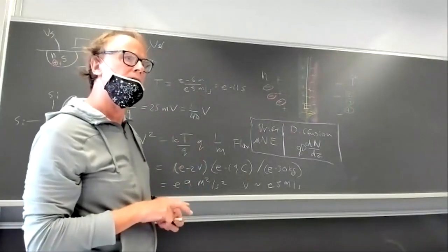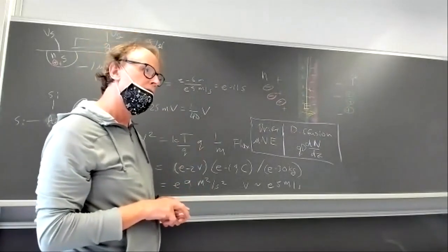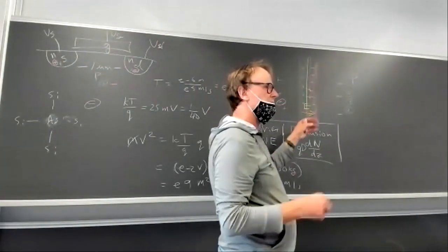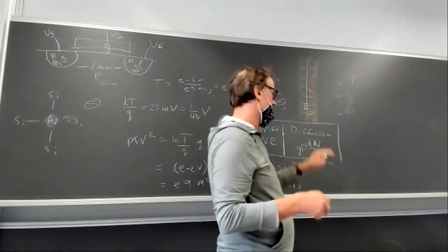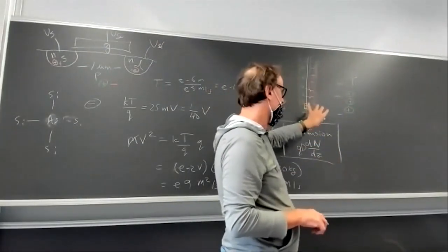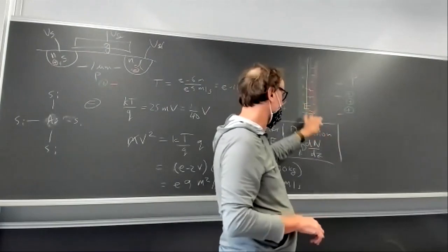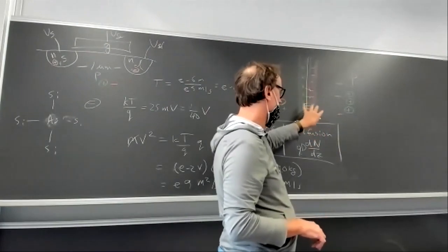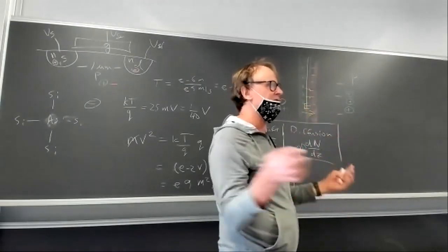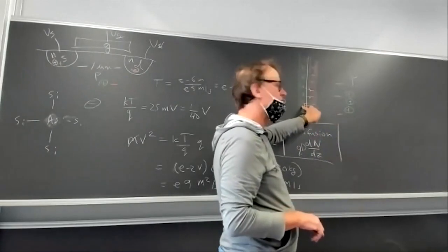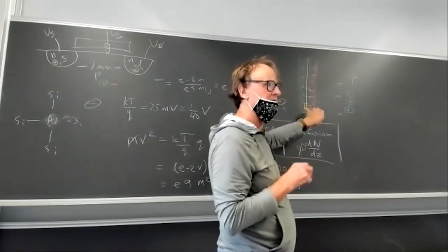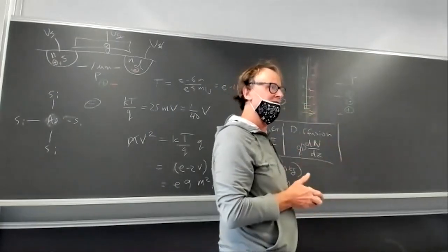You just said that these are the fixed particles. Aren't these the moving ones? No, there are particles whizzing through here, but they're in equilibrium, going through at a high speed. But what I'm drawing here are the fixed ions. And it turns out, I'll show you in a moment, that in this region the concentration of mobile carriers is very small because they're going at very high speed. The main charge you have in this depletion region are the fixed ions that are left behind, the nuclei of the atoms that are charged.